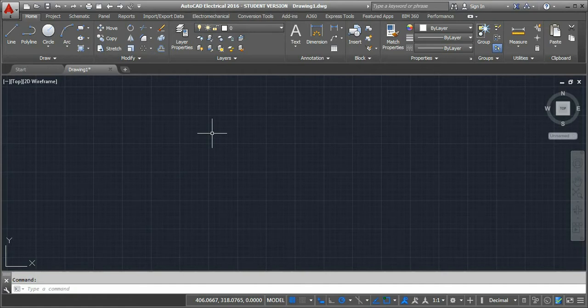Here we'll see in this video the keyboard shortcuts for AutoCAD. The drawing mode, here so many drawing modes are there. In the drawing mode we can have settings. Here we can use the function keys. So we have function keys F1 to F12 on our keyboard. These F1 to F12 keys can be used to toggle between some of the different drawing modes.